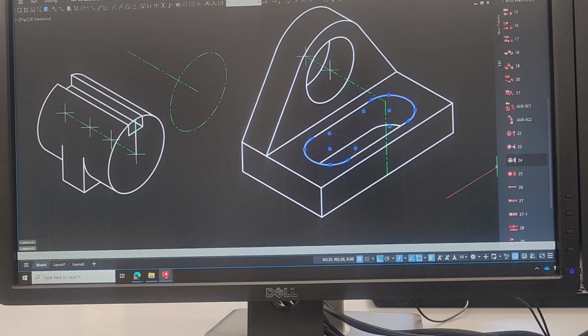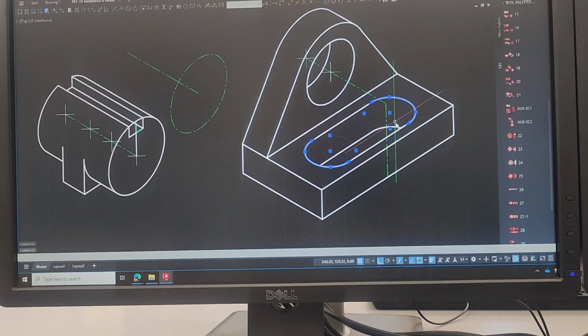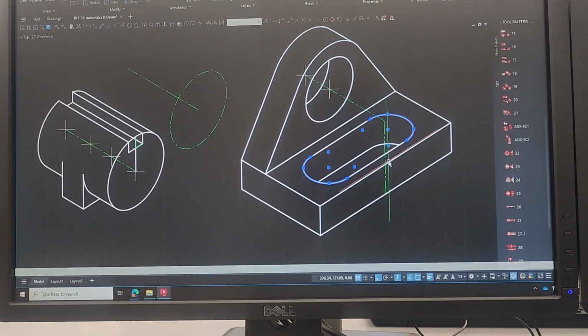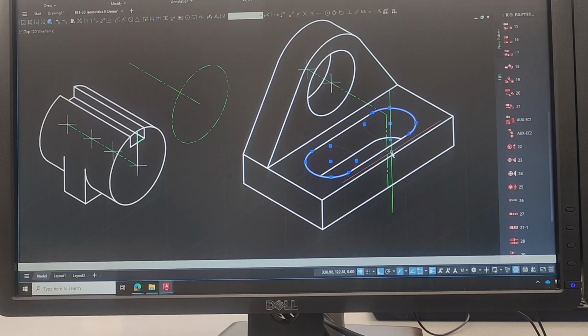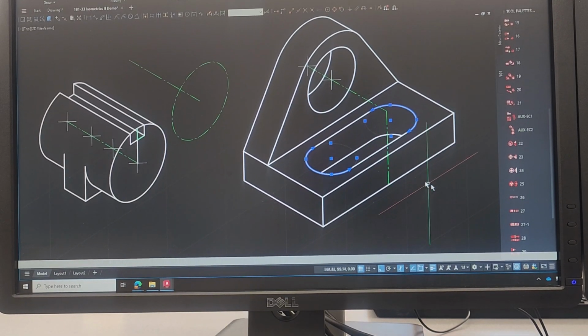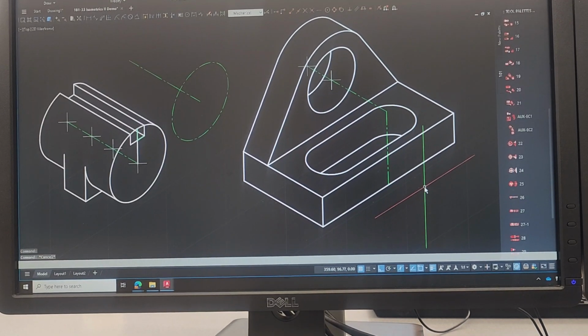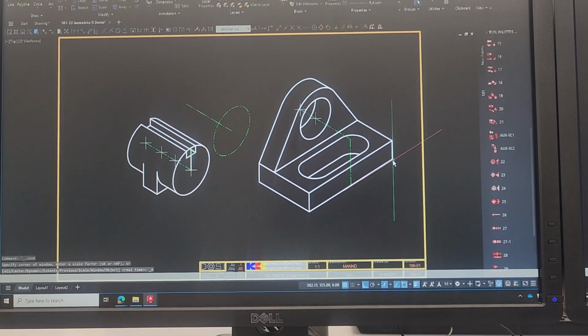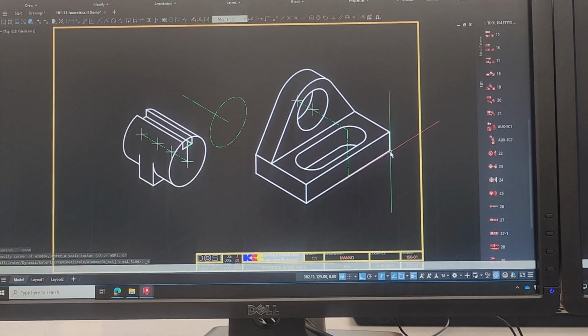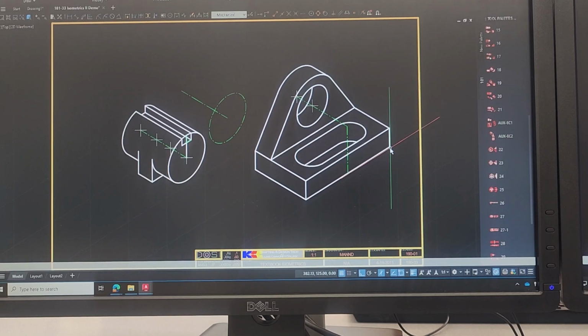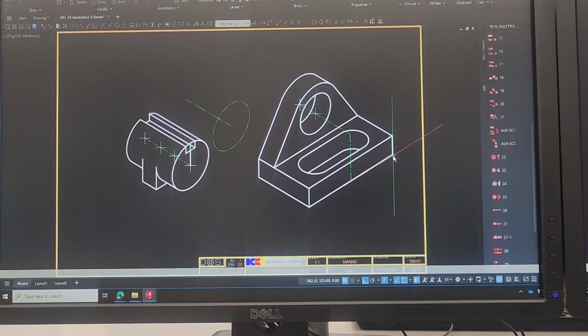And I know this depth over here is a value of 20 deep. I can simply go Z minus 20, and I can locate that whole thing by copying it, take it from its center point there, go down 20, and I see what I see back inside buried. So it's really not that complicated. In fact, I really don't need to spend any more time talking about it now unless you have any particular questions. So, you ready for me to shut up and let you attack it?